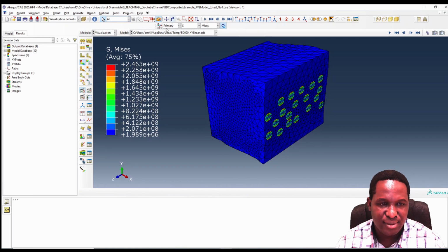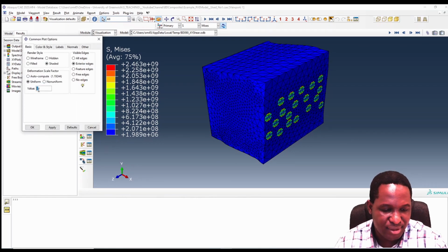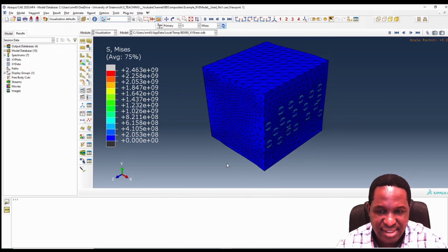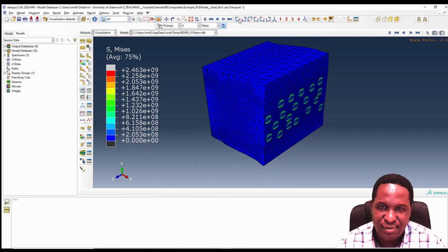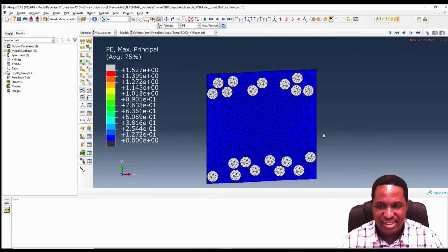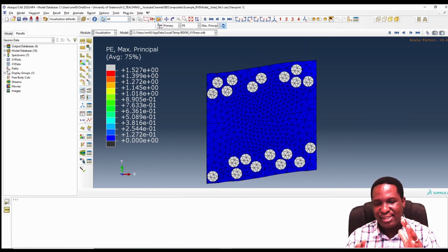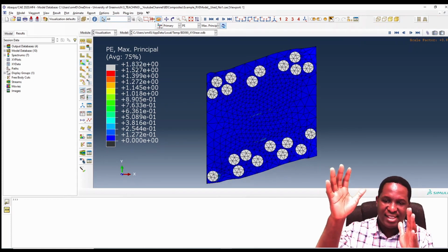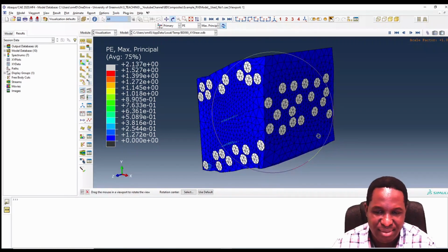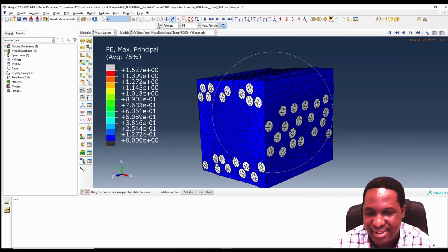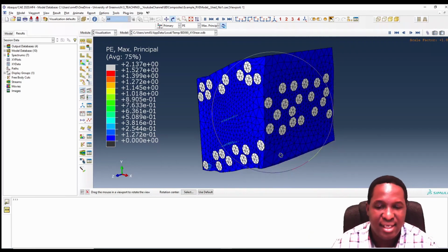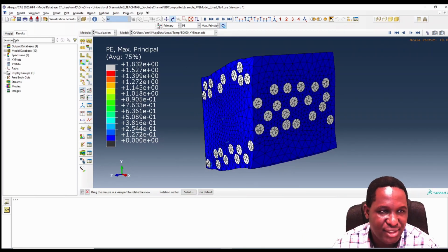So again, if you think about what's happening here, especially let's try and exaggerate this further, maybe to 3. Okay, so what's happening with the shear cases is that you're shearing upwards in this case. If you go in this plane, you could see there's a shear deformation going on in the model. You look at the plastic strain, so the fibers are basically being moved around as the system shears up and down. They again do not really offer significant reinforcement. They do offer some, but not as when you're loading in the main fiber axis. So clearly the back end is fixed, so these fibers are basically being bent and rotated. And so this is what you see with the XY shear plane.